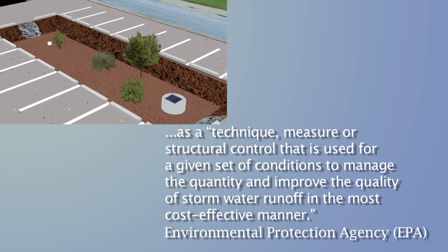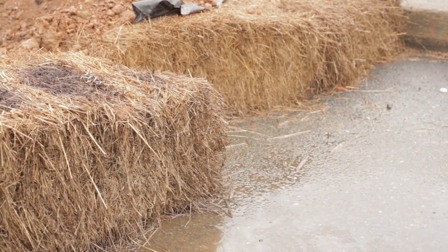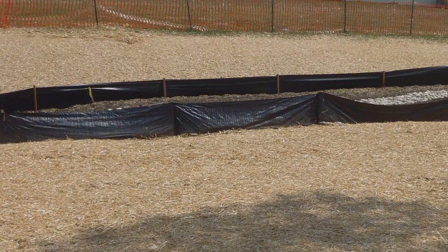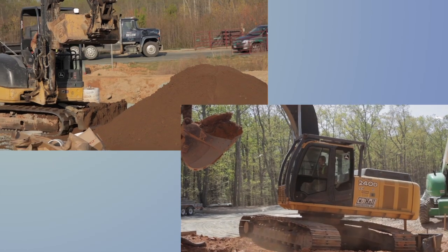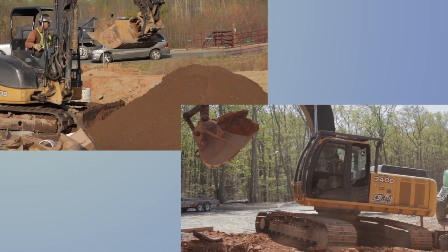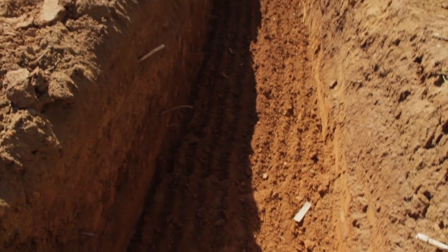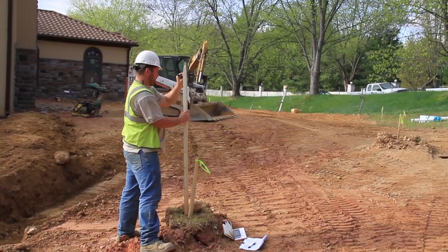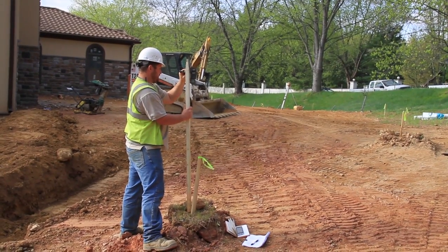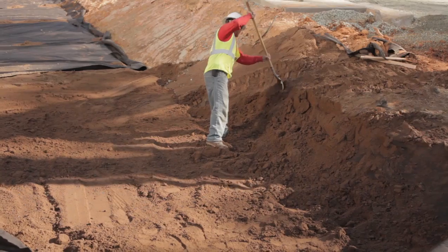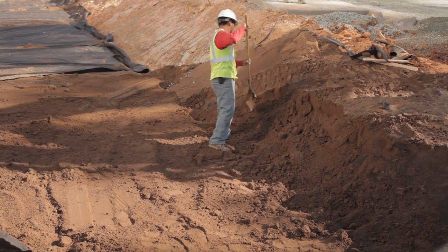In this stormwater practice construction video, we learned why people build stormwater LID projects, the importance of following the construction sequence, methods to keep sediment out of your stormwater BMP during construction, the benefits of different types of excavation equipment, how to use equipment to reduce site impact and improve project performance, the importance of checking elevations throughout the construction phase, how to avoid unnecessary compaction.